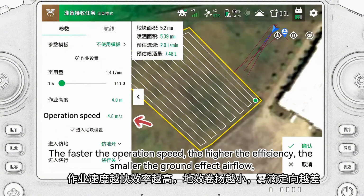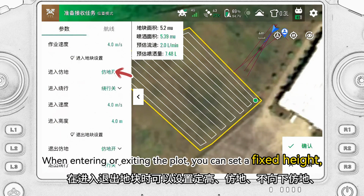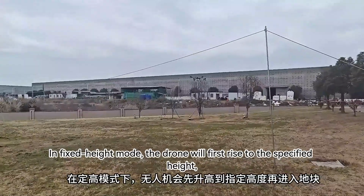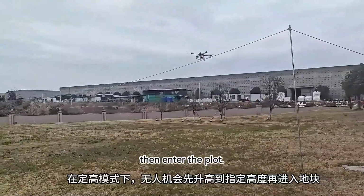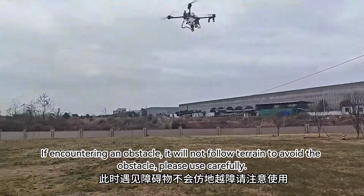The faster the operation speed, the higher the efficiency, the smaller the ground effect airflow, and the worse the drop directionality. When entering or exiting the plot, you can set a fixed height, terrain following, or not simulating terrain following. In fixed height mode, the drone will first rise to the specified height. Then enter the plot. If encountering an obstacle, it will not follow terrain to avoid the obstacle.